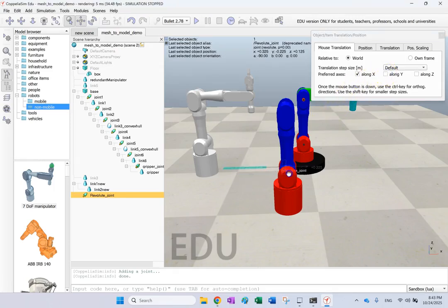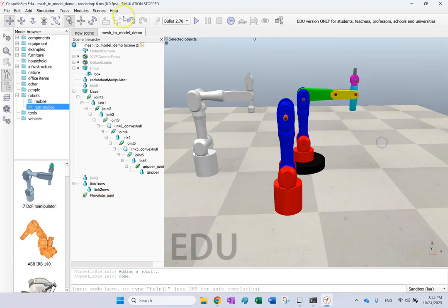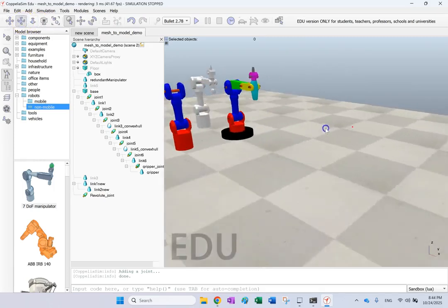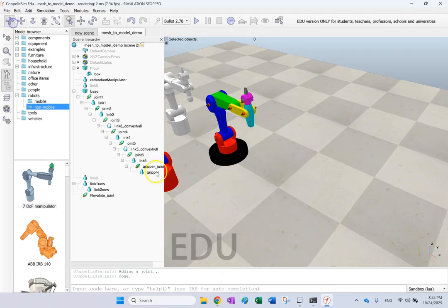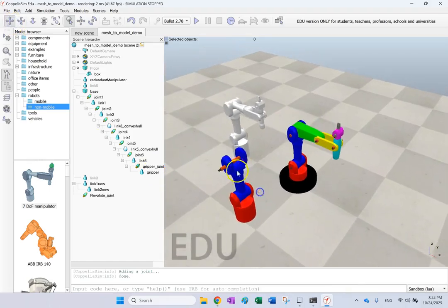So let me first bring it here. Maybe then I go up Z, come here, and then do Y. Now get it out of the part, no Z. So let's see, something like that. Now I just need to go back up in the Z direction, something like this. Okay, so let's say this is the proper location of the joint, and you can resize the joint if you want. You can make it longer, you can make it shorter, you can move it.